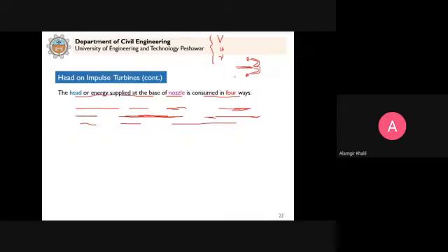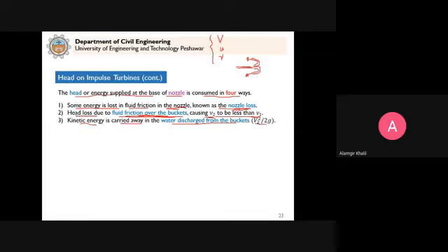So in this case, because the water flows with some velocity, it means not all of the kinetic energy is fully utilized. Because at the exit, the water still exits the buckets with a small absolute velocity. Actually, the water is striking the buckets with kinetic energy, so the water should leave with 0 velocity. In that case, the full kinetic energy will be transferred. But as the water exits with a very small velocity, v2, the absolute velocity, it means that not 100% of the kinetic energy that is supplied is transferred to the runner.